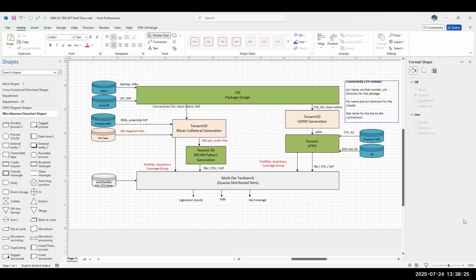So if you had a defect on that device, maybe running at-speed testing on that, you'd still have to throw the part out with the interposer, but at least you're not throwing 4 good HBM memories away. Even in the TSMC spec, they support top side and bottom side. Their format allows the probe pad to be at the C4 bump side of that interposer.